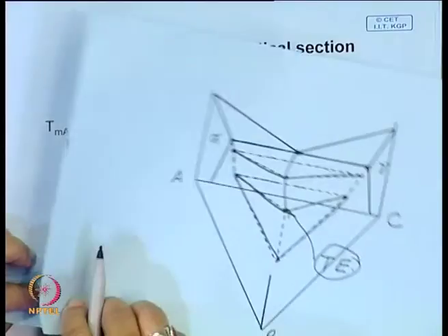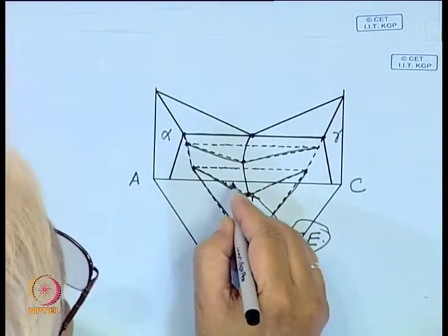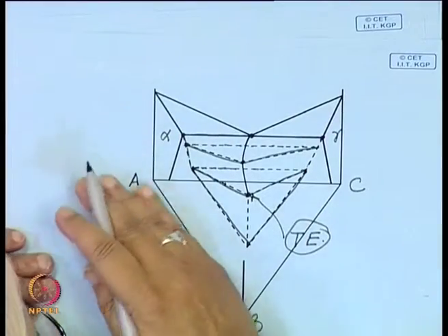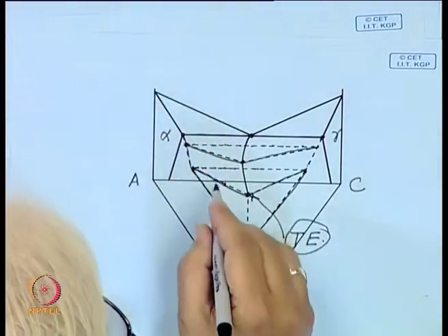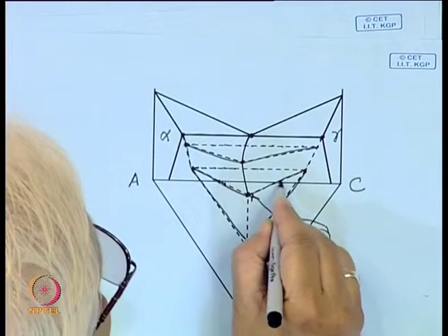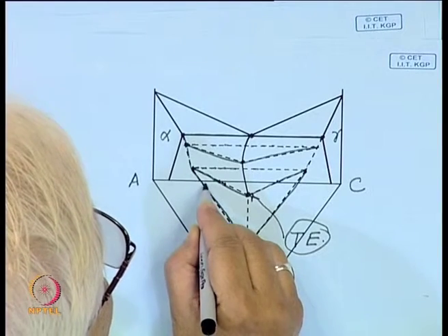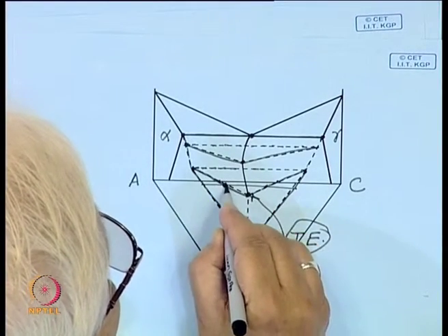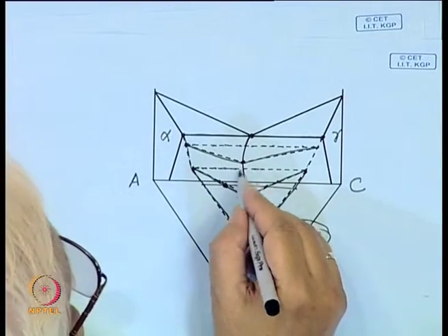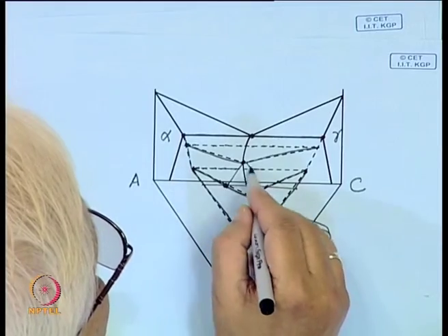If we come back, similarly, there will be a similar surface coming down from that AB eutectic, and they meet at this point. Somewhere here they will meet, and at this isotherm they will meet. So, that vertical section will look something like this,